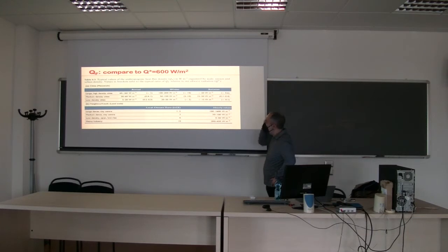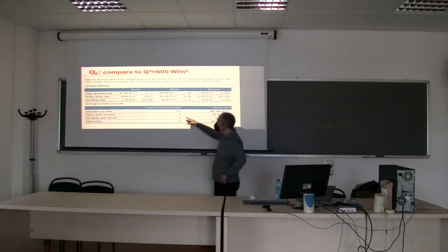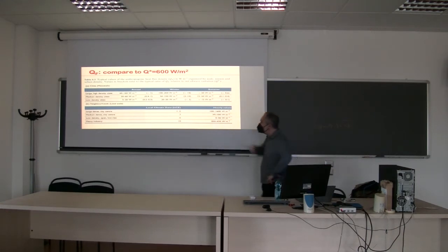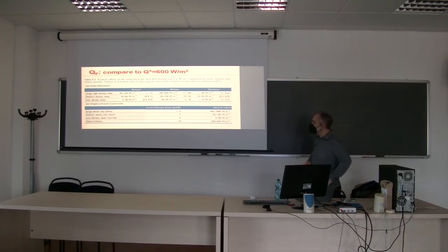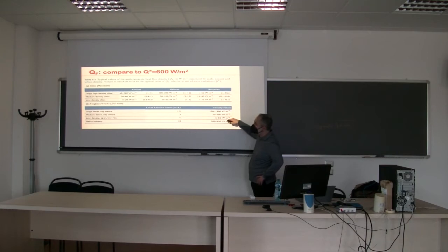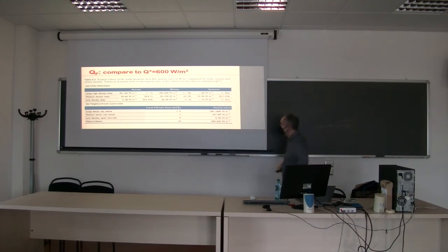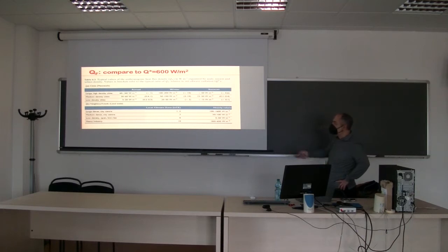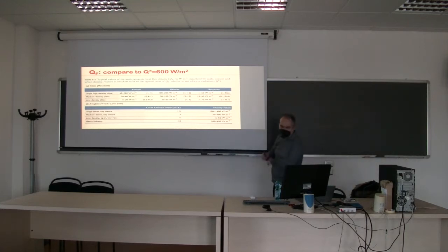anthropogenic heat. This is also given in terms of what Oak calls the local climate zones. I talk about this concept in other lectures. It's not very critical here. But basically you see that when you go large, medium, low density, or a heavy industrial area, these decrease if it's residential, and if it's commercial, it will actually increase again to about 300 to 600 watt per meter square. But there's a lot of uncertainty, and this is a topic of continuing research if you want estimating QF.